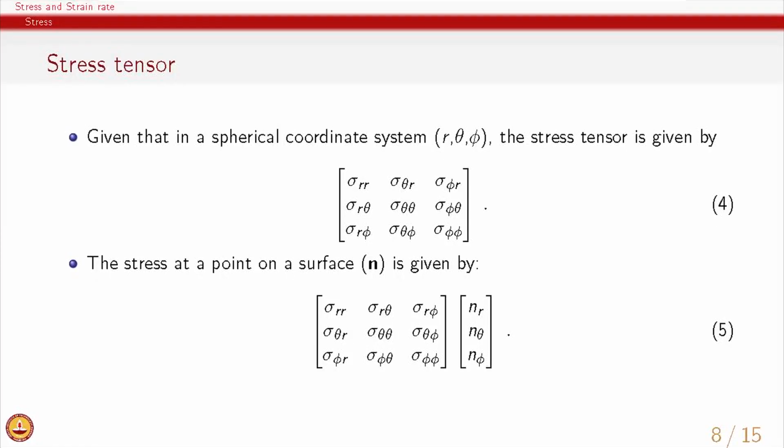and as a preliminary observation, we will see that cone and plate device is where shear flow is observed. So, since theta and phi are the dominant components, one of them being velocity direction, the other one being direction of the shear, we will see that sigma theta phi or sigma phi theta will be the two dominant components which will be discussed.